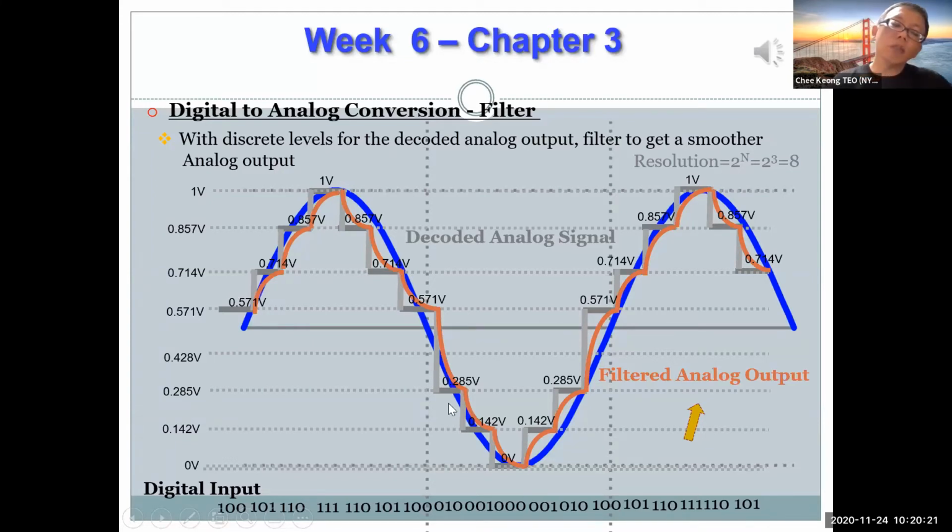So this is to illustrate to you that even without a resistor, with a simple C charging and discharging, you can see that the actual result that we want to get is the blue line, right? But the staircase signal, of course, has a lot more error as compared to your RC filter, because the RC filter actually has less error compared to your staircase signal. So essentially, the filter is the way to go. If you put in enough R, then the cutoff frequency moves nearer to cut away more harmonics, then essentially you will get a smooth signal. Follow me so far?